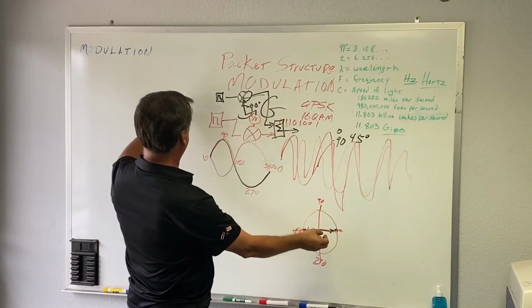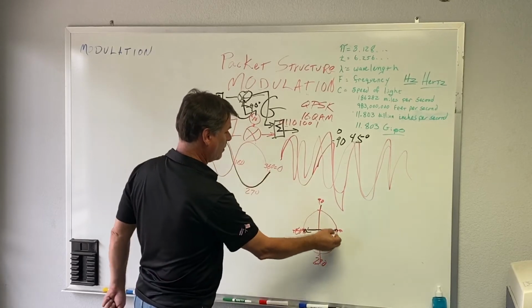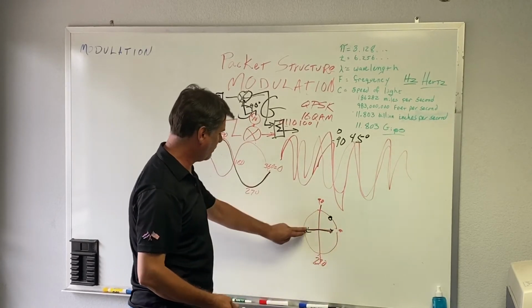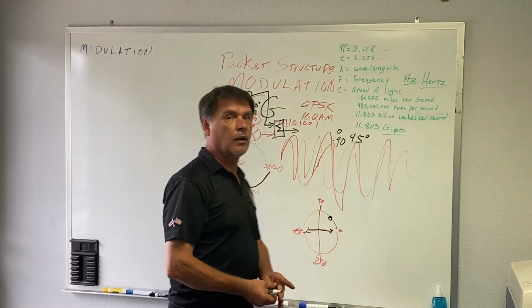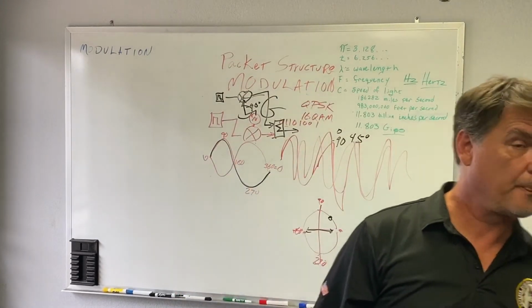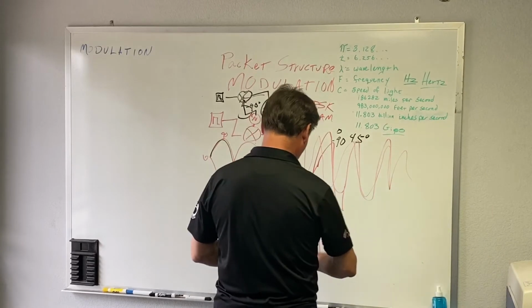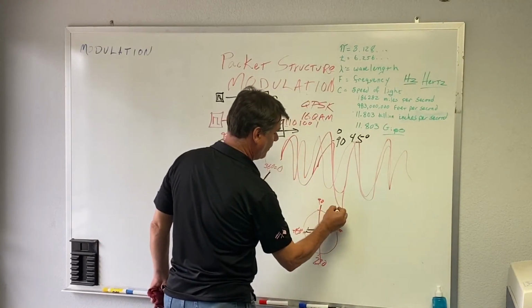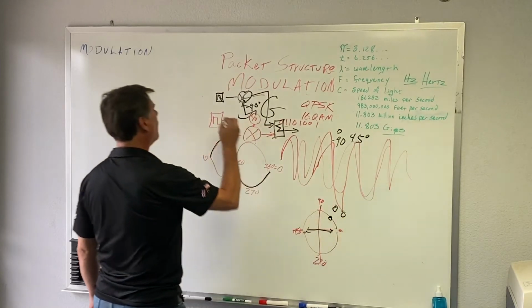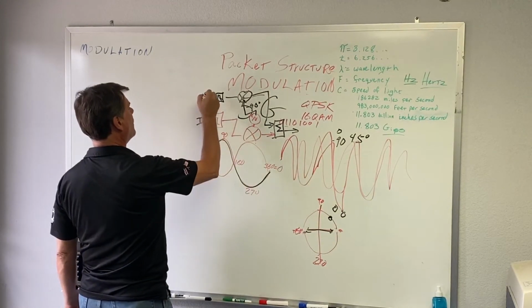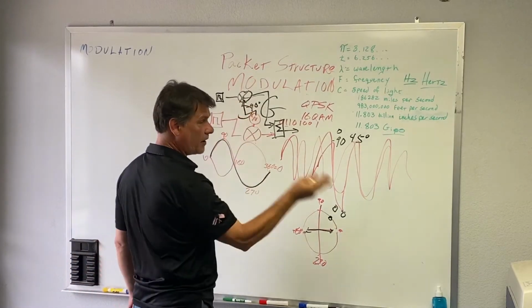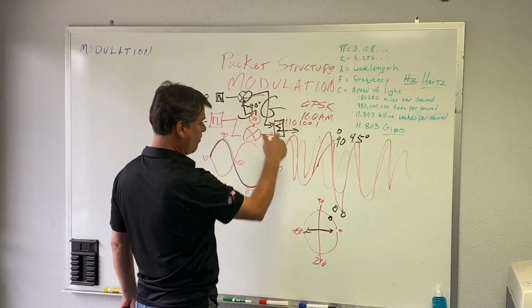Which means 0 in there, 0 in there, your first vector is right there at 45. This one doesn't exist anymore. So, if you change this, this is at 0, 0, 0. And we'll call these the I stream and the Q stream, in phase and quadrature. So this one's shifted 90 degrees. It's shifted up 1 quadrant.